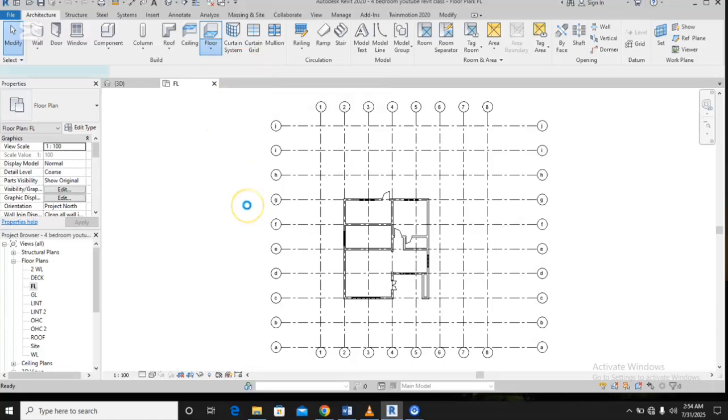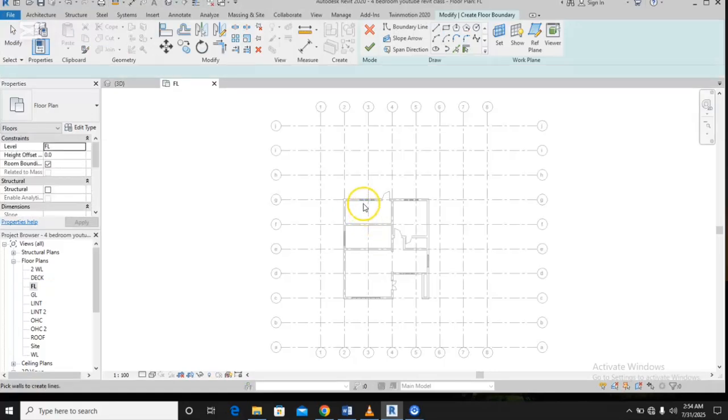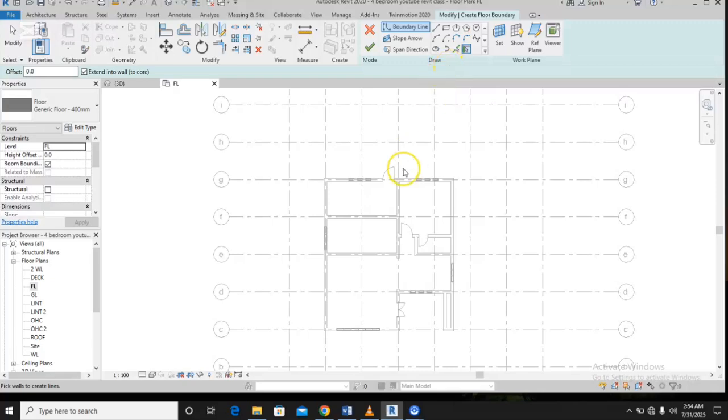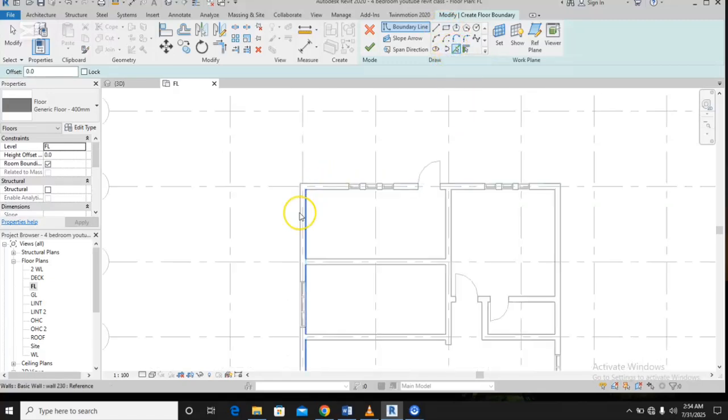When you click on it, it's just the normal way we are used to editing our wall, windows, and all these things. Before the editing, we're going to select the area for the floor. I used to use pick line so that I can get it at the edge here, but you can use sketch line, normal line. If I click at this edge, it will be at the sharp edge. But what I usually do, I edit it to 25. I want a small extrusion, so I'll just place like 25 or 20 millimeters.